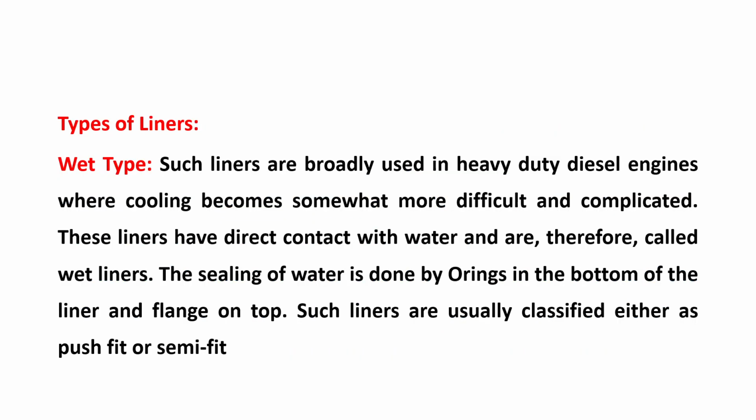The liners are normally of two types, wet and dry. The wet type is normally used in heavy duty diesel engines. These liners have direct contact with the water, so they are called wet liners. O-rings are present on the liner, and the flange is at the top.